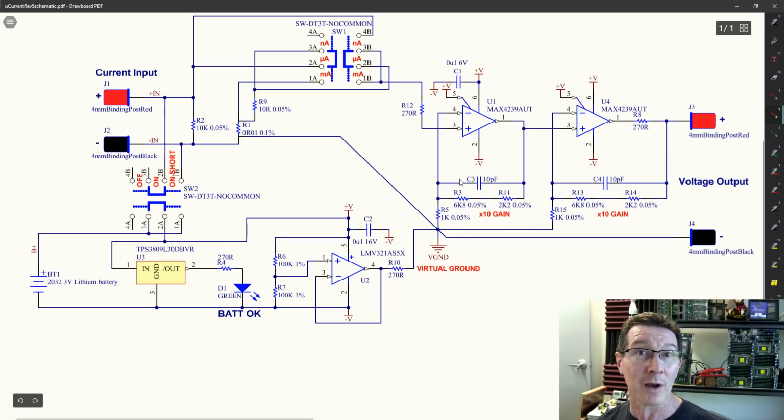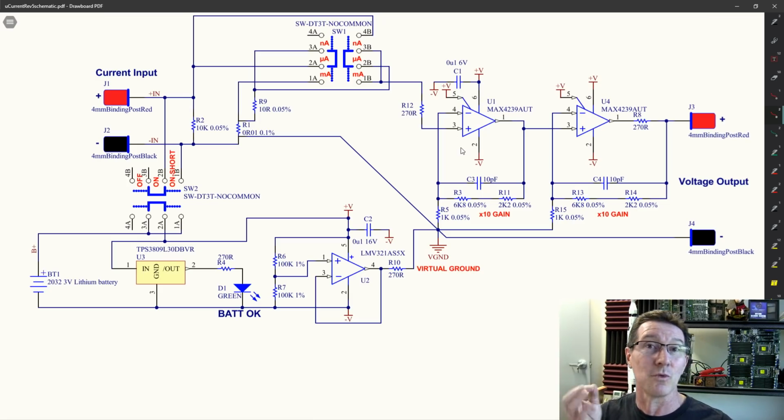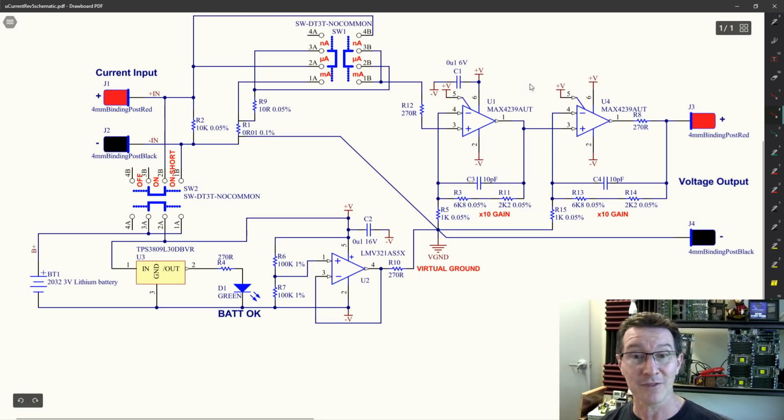So it had 0.1 microvolts typical offset, as we'll go into, and that changes a little bit when you cascade them in series like this. But the good thing about the µCurrent, and the reason it's relatively expensive for the type of parts in here, is that the parts used in it are quite expensive, so that you don't have to do any calibration, trimming or anything like that. So yeah, we're going to do a video just looking around the market for op-amps.